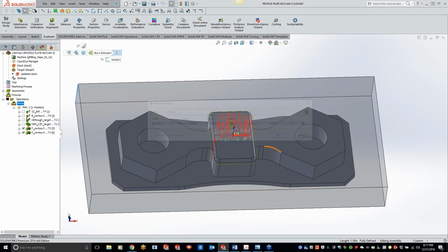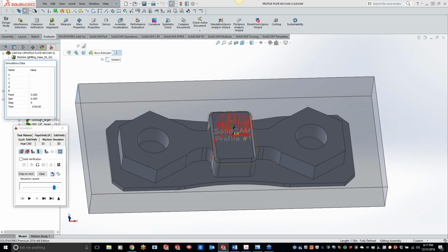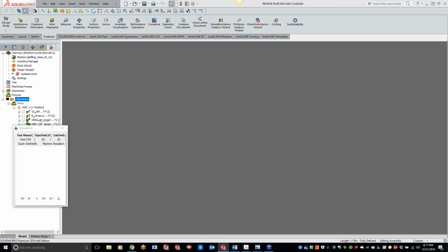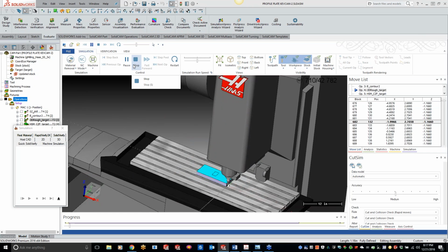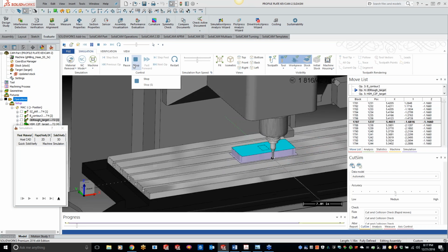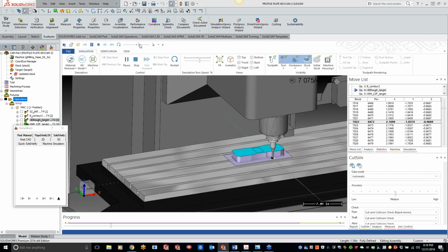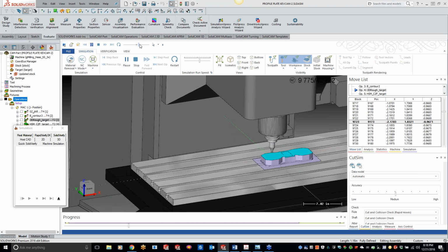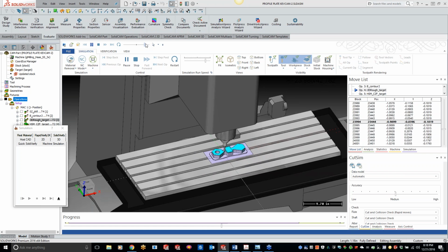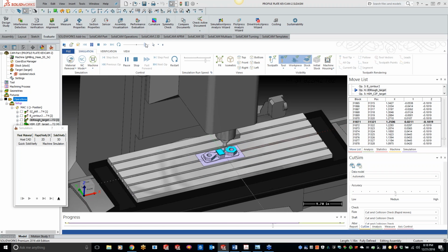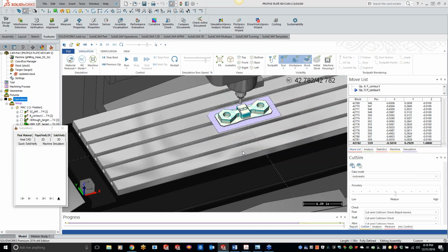Absolutely. All right, let's get that set up and we'll run this through Machine Sim. Then I'm going to bring up that other part here and show you the difference. So let's go ahead and do Simulate, Machine Sim. Okay, let's slow it down a little bit here. Probing up our part and utilizing our iMachining. So we can speed up a little bit here. Doing that helical entry, getting that face topped off there, and using that HSM to get a nice pretty finish, engraving, and we're done.